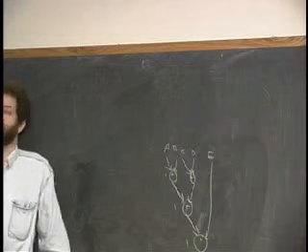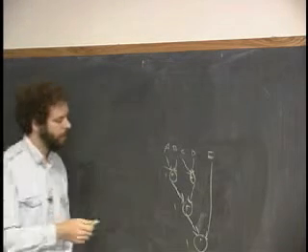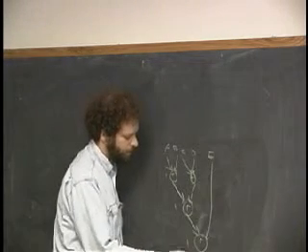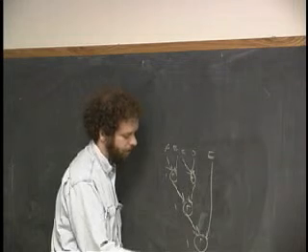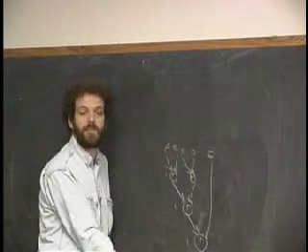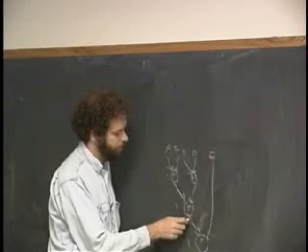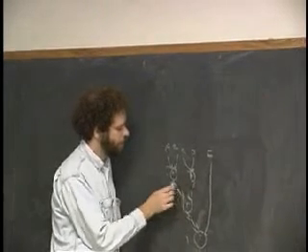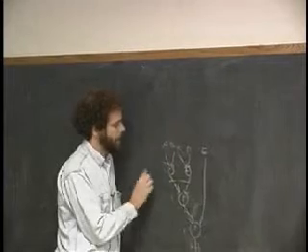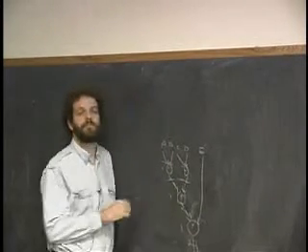And now I want to pipeline it. Okay? So I say, okay, let's do it. We're going to put a register on the output because that's kind of the conventional thing to do, so that when we feed the next stage, we'll have a register. And we'll put one over here, and we'll put one in each of these places, and then we're done.